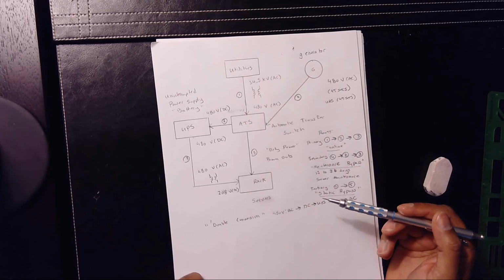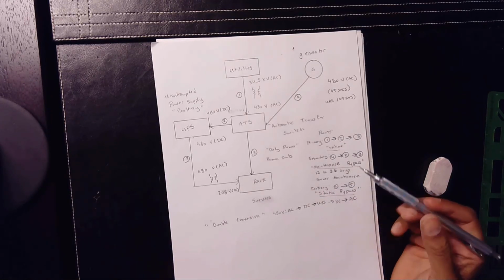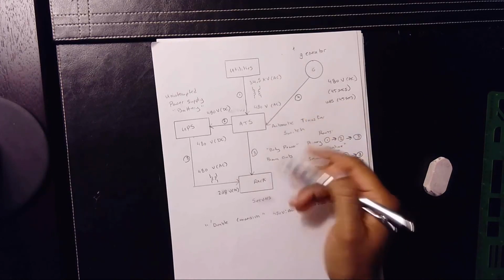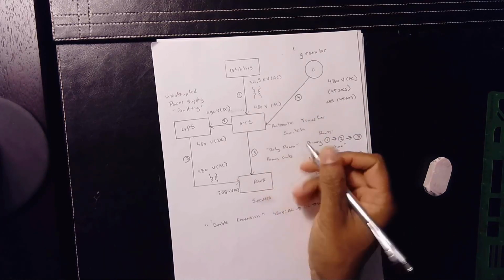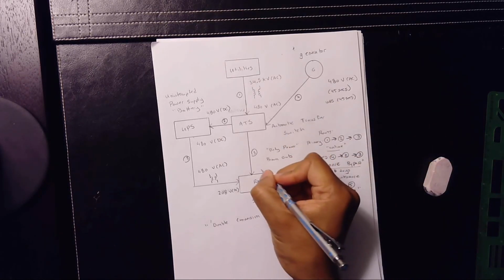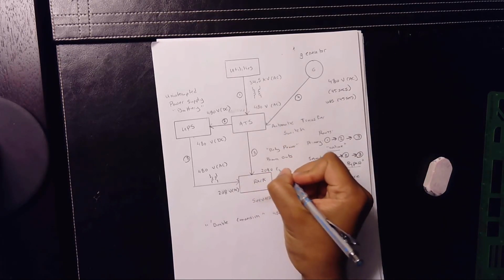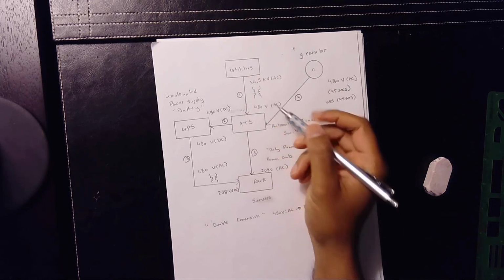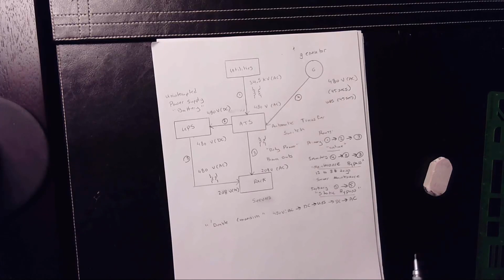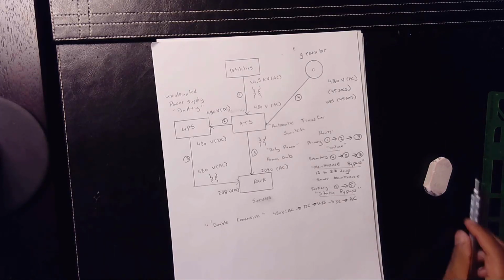Now, in a regular scenario, anyway, from 480, obviously it has to come down to 208 volts. I mean, it's got no choice, right? So from 480 volts here on the static bypass, this has to be 208 volts AC. And this is obviously another set of inductors here, right? So it's straightforward. So know this stuff, study it, okay?